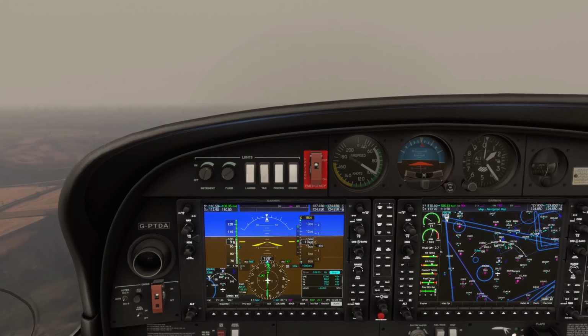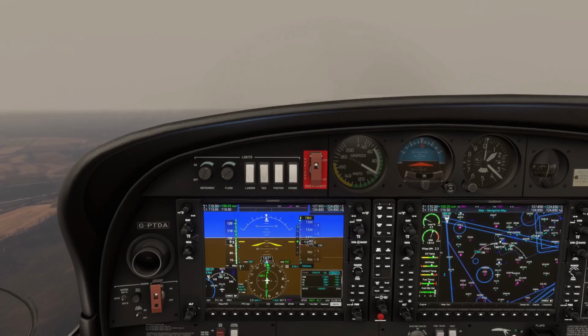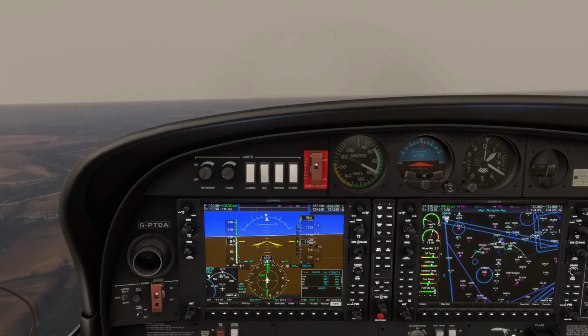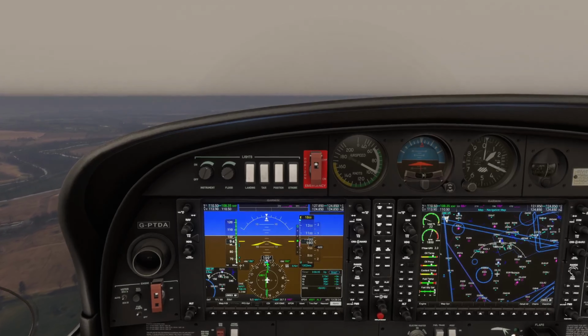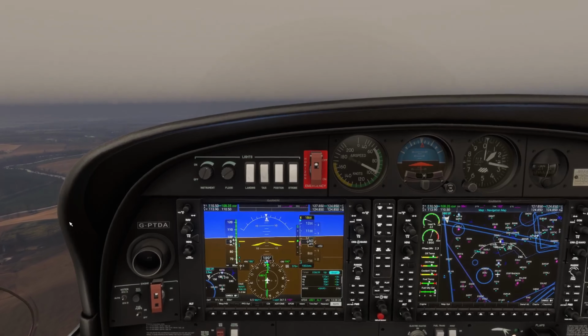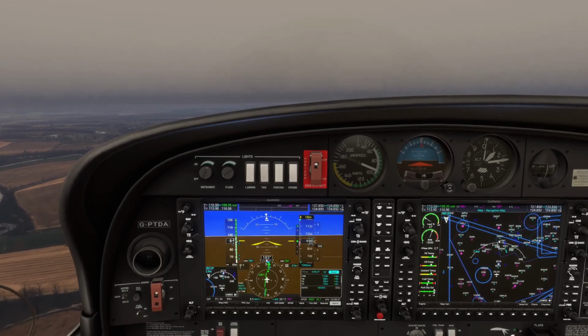We've got the localiser coming through 1,000 feet. RVR's already above requirements, so we don't need to do the approach band check. However, 1,000 feet we are stable, so we can continue the approach for now. If we were unstable at this point, we would go around. So we're slightly right of track, so we're going to make a small adjustment to the left. As you can see, look how sensitive it will move.